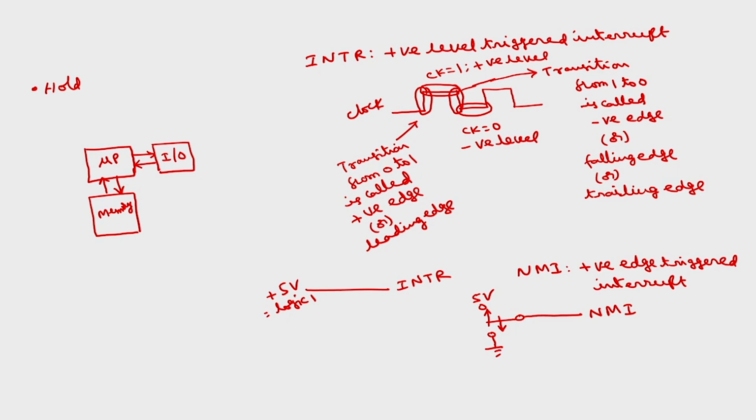As I have told, a microprocessor is useless unless it is connected to memory and IO. Because the microprocessor has address and data buses, if the memory wants to transfer data to the IO, the regular process is that first memory transfers the data to the microprocessor, then from the microprocessor the data goes to IO.